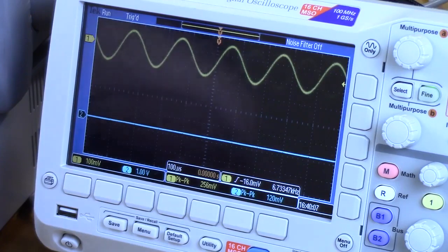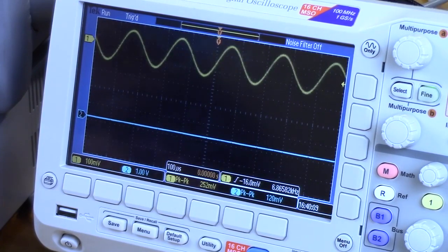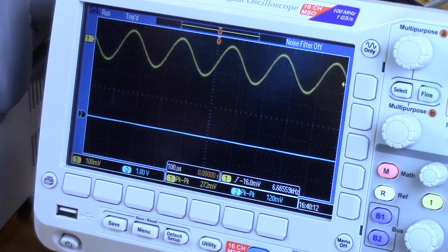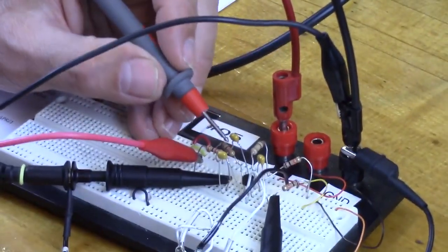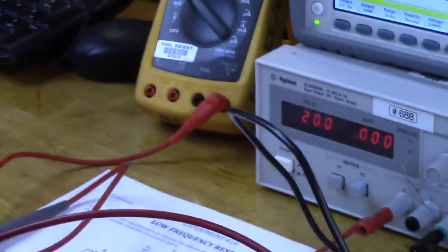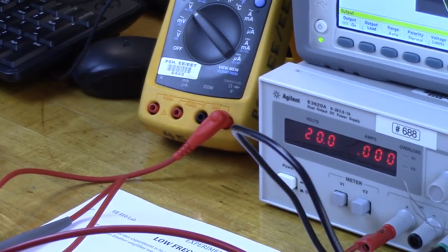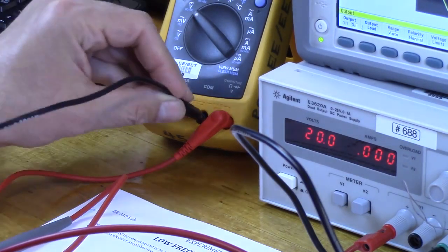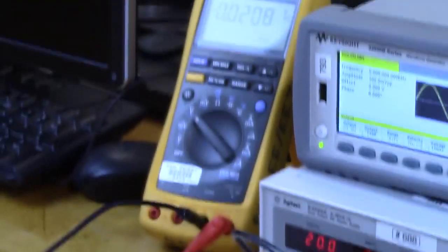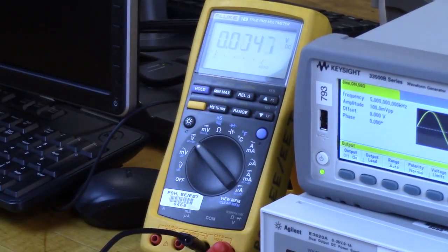So we're going to put our multimeter on DC volts, and we're just going to temporarily put this on the emitter, right? Not there. Oh, that's right. We need one more banana plug. Where are they? Oh, actually, there's one here. So let's ground our voltmeter, but let's ground it over here just to keep it away from the circuit board.